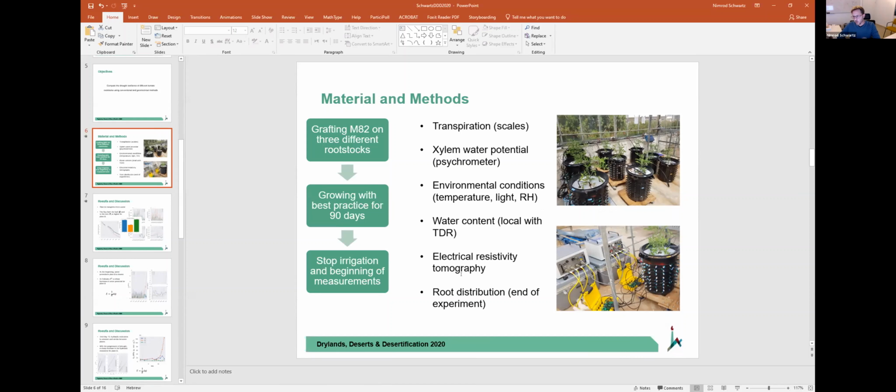The only thing that we want to obtain is good contact between the electrode and the soil. So in this method, an important step is to make sure that you have good contact resistance between the electrodes and the soil. Okay, cool. So you don't affect the soil too much then?